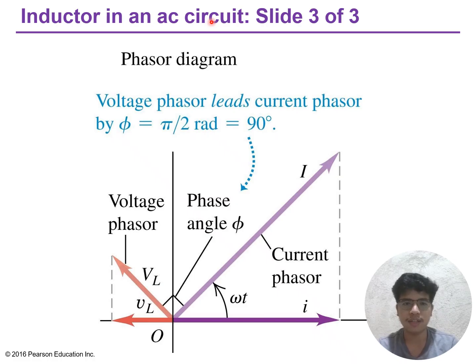When voltage reaches its minimum, the current is decreasing back to zero, and finally when voltage completes its cycle returning to the maximum, the current is at its minimum. This continuous phase separation throughout oscillation reflects the inductor's continuous opposition to current changes.